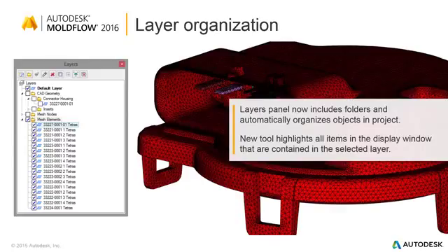Additionally, if you bring in a CAD model now from, let's say, ProEngineer or SolidWorks, and it has multiple bodies in it, we automatically include the name of the original components from the way it's called in ProE. We transfer it also into Moldflow. Where in the past it was called Body 1, Body 2, Body 3, CAD Body 1, 2, 3, now it will be called Parts, Mold, or whatever you named it in ProEngineer. So that makes the connection with the CAD model a heck of a lot easier.